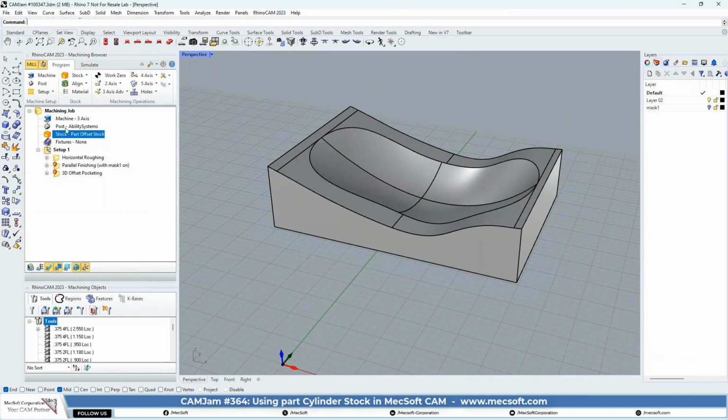You can go ahead and use the stock part offset and add that 50 thousandths to the part model and then machine it so that you can do the simulation similar to the way you were doing it for a casting. Okay, I hope that makes sense.